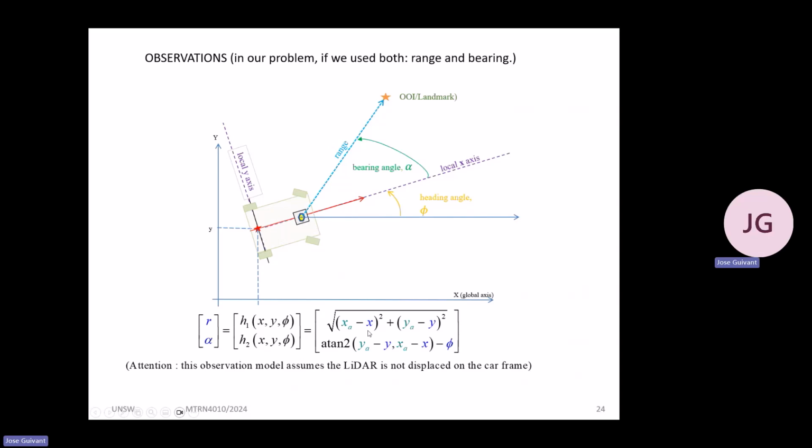in the global coordinate frame, with respect to the position of the landmark, also in the global coordinate frame, which corresponds to the same distance that happened in the local coordinate frame. Because now I'm at 0, 0, and this object of interest is being represented or detected in my car coordinate frame. So I have the position of this object of interest in my car coordinate frame, so that this distance corresponds to the same distance, or the distance between my position and the position of the object of interest in global coordinate frame. And because I do know that that object of interest corresponds to certain landmark, I'm going to exploit that.